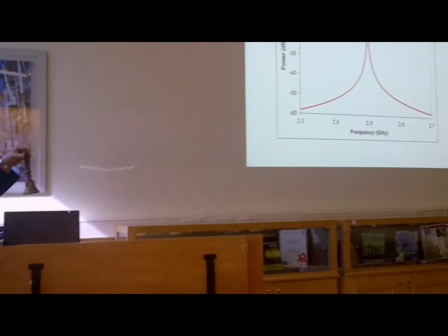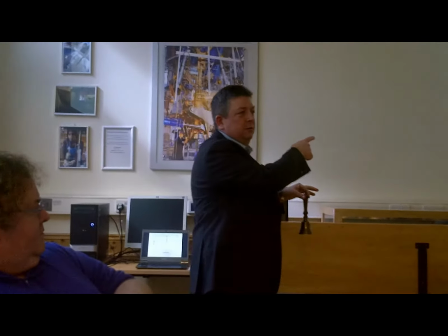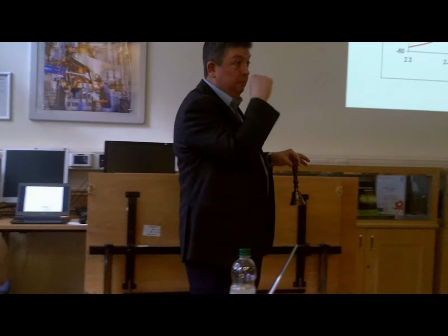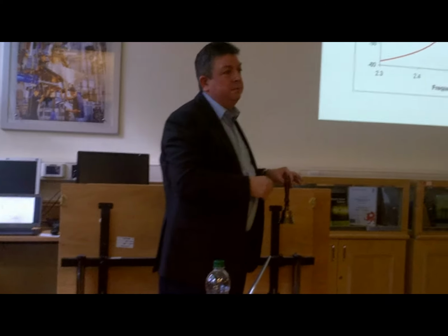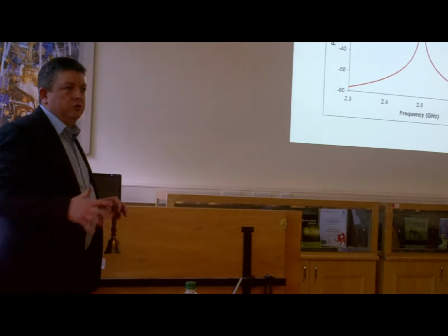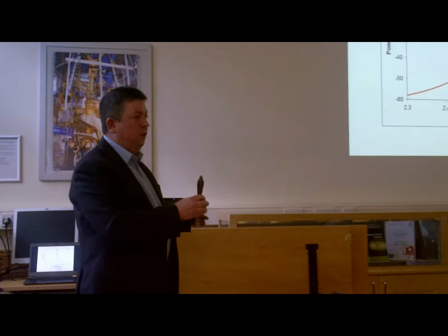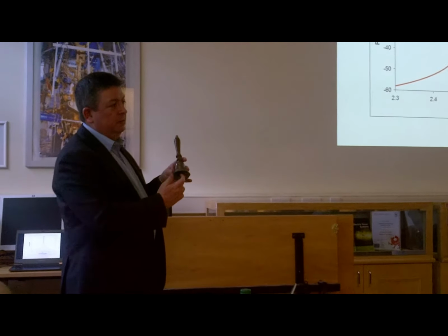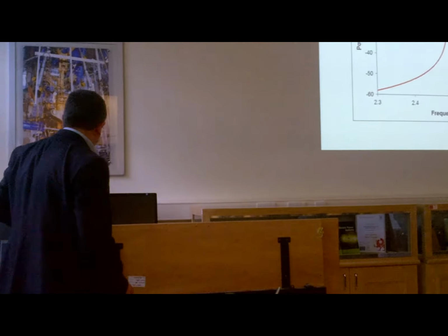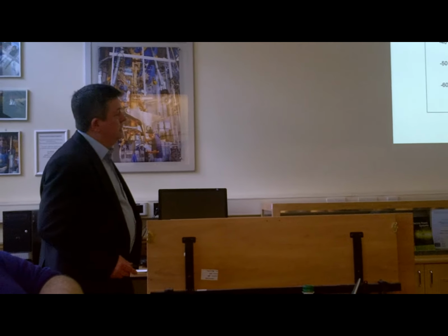So again, going back to a bit of the physics really, in terms of what this measurement tells us. It's nice to think of the empty cavity as producing a ping. We always think of acoustic resonators. I've brought a bell along with me just to illustrate this. That's a nice high Q resonance. Okay, those ping, and the spectrum of that acoustically would look like that, albeit at lower frequencies. So that's a high Q resonance. The Q factor is basically the frequency divided by the bandwidth. And the Q of these microwave cavities tends to be of the order of 10,000 or something.